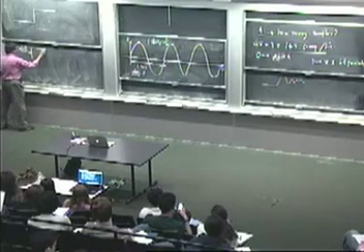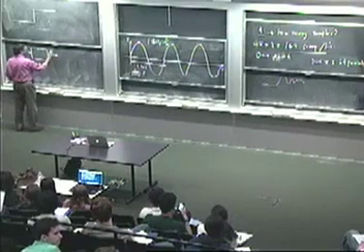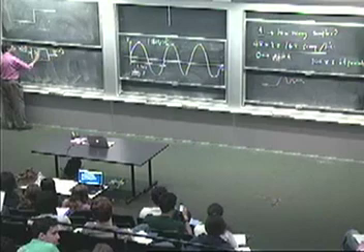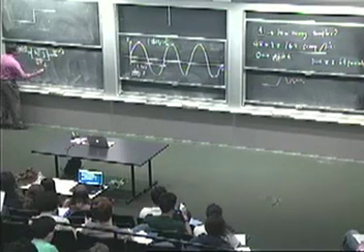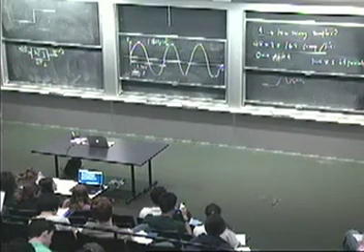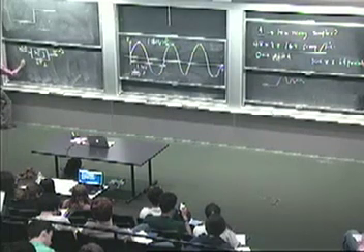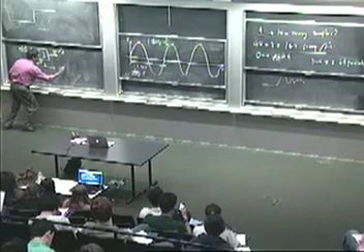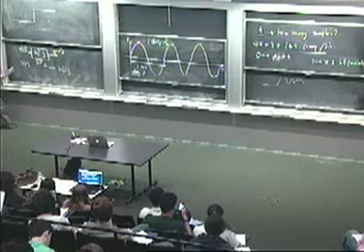And still in the time domain, next time we'll start to look at this in the frequency domain. Harry mentioned frequency several times here. So we're talking about an LTI channel, linear and time invariant. We talked about characterizing it by its unit sample response. Unit sample response means put in a unit sample function, you get out an output that you're going to call the unit sample response.